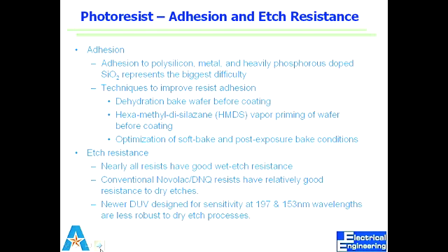We want resist to adhere, for many different reasons. For etching, we don't want any of that chemical to seep through, right? And how do we make adhesion better? We have to first get rid of all water vapor before we apply photoresist.